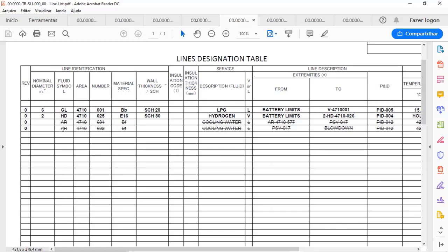I'll talk about the P&ID further, but the line list prevents the chemical process engineer from duplicating information for different things. For instance, I have a sheet B01 with line 001 and sheet F5 with the same line identification. So when you are developing your piping instrumentation diagram, most often you do that using the line list side by side, and that will prevent you from duplicating information and making your job harder.